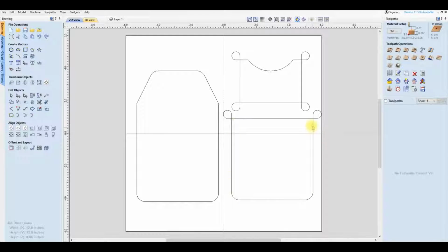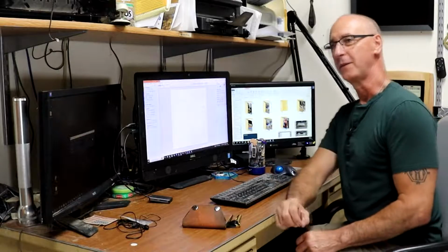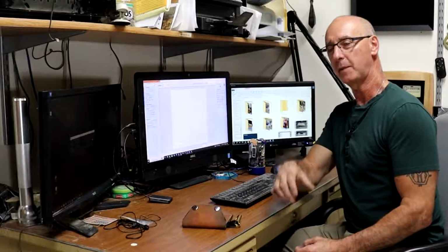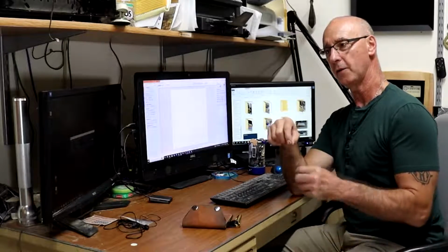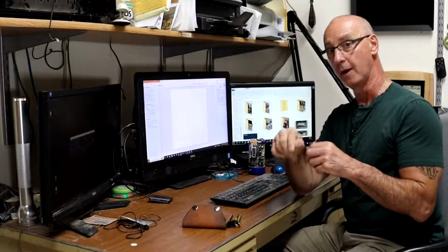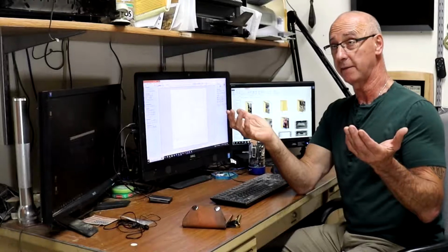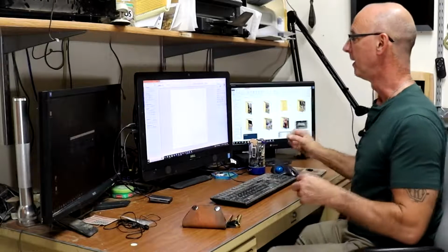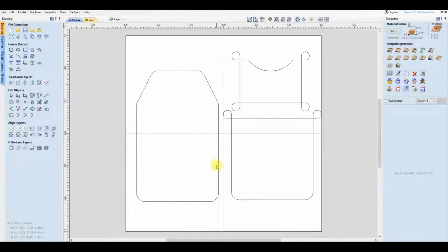Make this curve, come up here, out, turn, come back. So this is a great workaround because it provides a way for the knife to make that sharp corner, and we don't have to run the drag knife gadget if you don't want to. So again, we can use the profile toolpath to make all this happen.